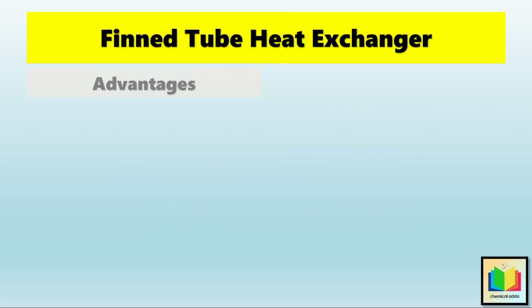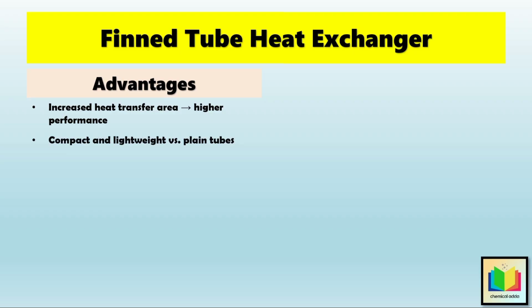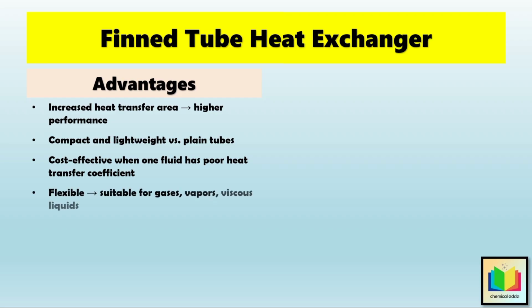So, fin tube heat exchangers offer several important benefits. So, the first advantage is, as we know, since fins provide an increased heat transfer area, they improve performance without making the exchanger bulky. And as a result, the equipment becomes compact and lightweight compared to plain tube exchangers. Then next advantage is, they are also a cost-effective solution when one of the fluids has a poor heat transfer coefficient, because fins help compensate for the limitation. Then another advantage is their flexibility, so the fin tube heat exchanger can handle gases, vapors, and even viscous liquids, while operating reliably under a wide range of temperatures and pressures.